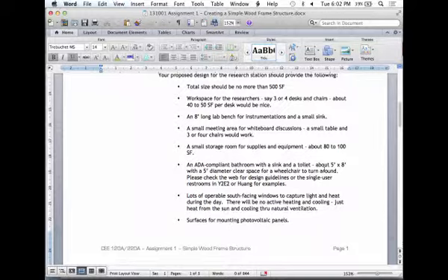If you're wondering what one of these looks like, go over by Koopa, those single restrooms there, or even over in Long. Most of the single restrooms on campus are ADA compliant, so take a look at how they're arranged. You have a wall-hung toilet, and there's some room to maneuver around. The sink will be wall-mounted, without a cabinet underneath it. There's also a lot of good guidance on the web. So just allow enough room. A teeny tiny squishy bathroom probably won't be big enough to get a wheelchair in. So try to be sensitive to that.